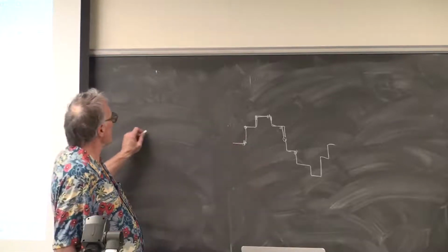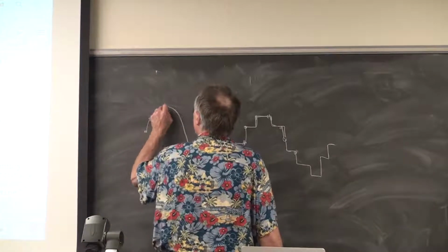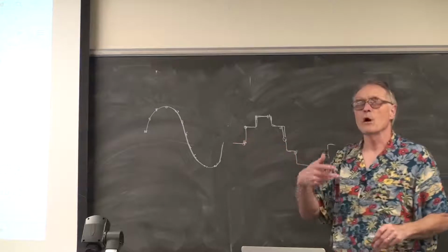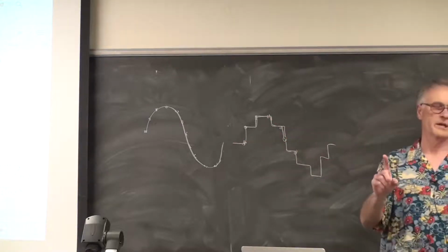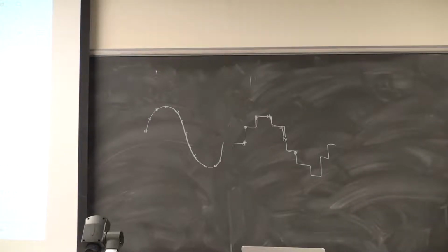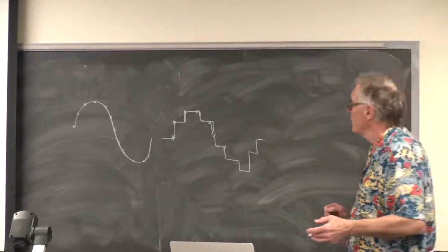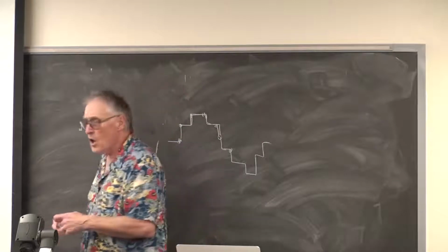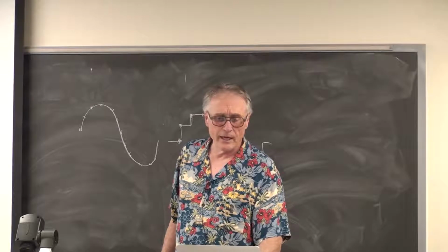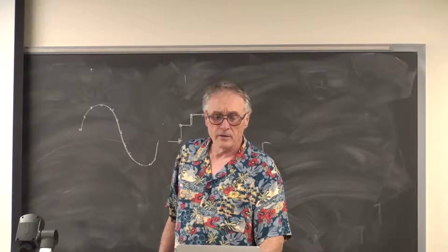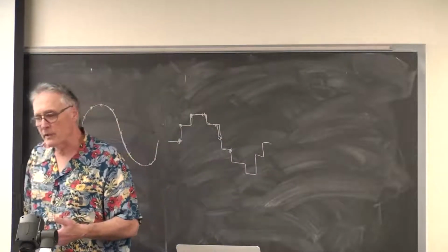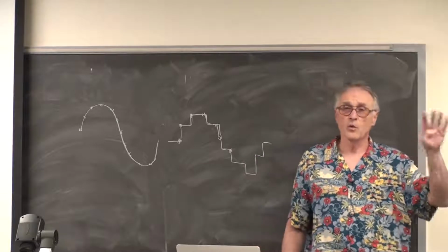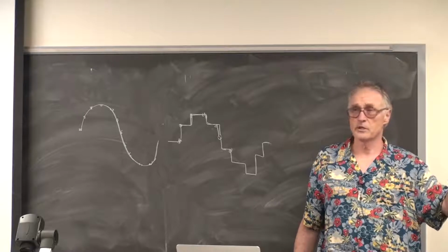So if you were to sample a sine wave at a finite number of points, the waveform which came out of the DAC would actually be a stepwise approximation of the sine wave, which is, thinking back to 2200, equivalent to modulating a sine wave by a square wave, multiplying them together. And so the spectrum gets complicated. And the reason for bringing this up is that crickets make a relatively pure sine wave. I would like the sine wave you synthesize to have all of the error terms, all of the bogus spectral components, 20 dBs down from the true frequency you're trying to generate.